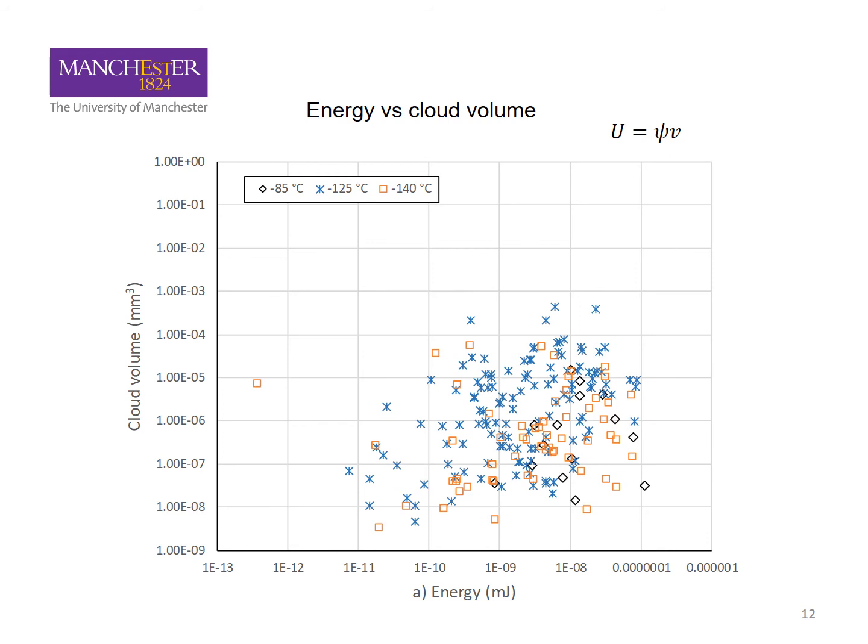Unfortunately, we don't know exactly when the particles nucleated, so all of these strain energy densities are calculated at the end of the FE simulation at the point the test terminated, not necessarily when the particle failed and the microcrack cloud nucleated.